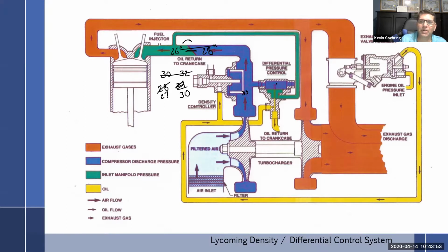And so differential's always looking to get the differential. And at some point, the differential pressure is going to be not satisfied and it's going to say, hey, we need more turbo. But yet the density is going to say, well, wait a minute. Now we need to think this through. No, we've got the density maxed out on this because of one factor or another. And no, we're not going to do that. So that one takes over.